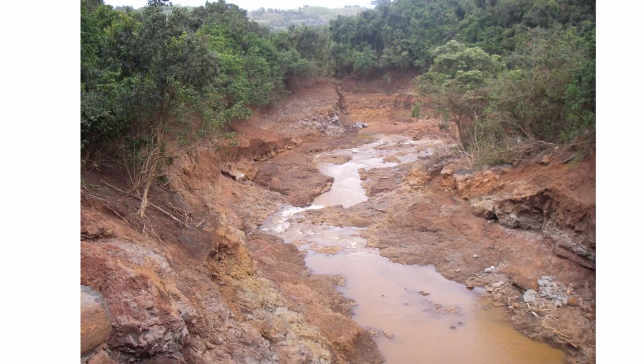Here's a picture of a channel that's kind of in rough shape. You can see that there's been some scour, that a lot of land has been moved downstream when the rain floods. When the rain is falling hard, it sends a big stream event through this channel, and the erosive force of the water as it moves downstream is taking soil and rocks and sediment along with it. So this is just an illustration that the soil sometimes doesn't have the internal strength to resist the scouring effect of the water.